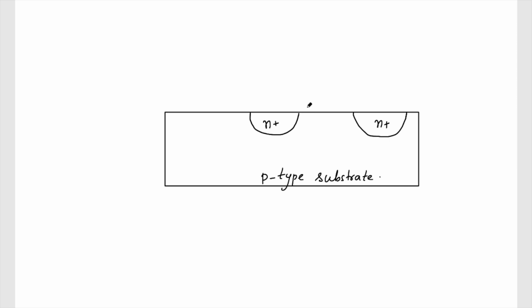Now this is my p-type, and then I'll have an oxide. This oxide is an insulator. This is SiO2, similar to what we have in glass. SiO2 is basically an insulator, and it is from silicon. On top of that we have our metal. So I have this metal, then oxide, and the semiconductor. For a homogeneous structure, where everything is made of silicon, this metal is also manufactured using silicon itself.